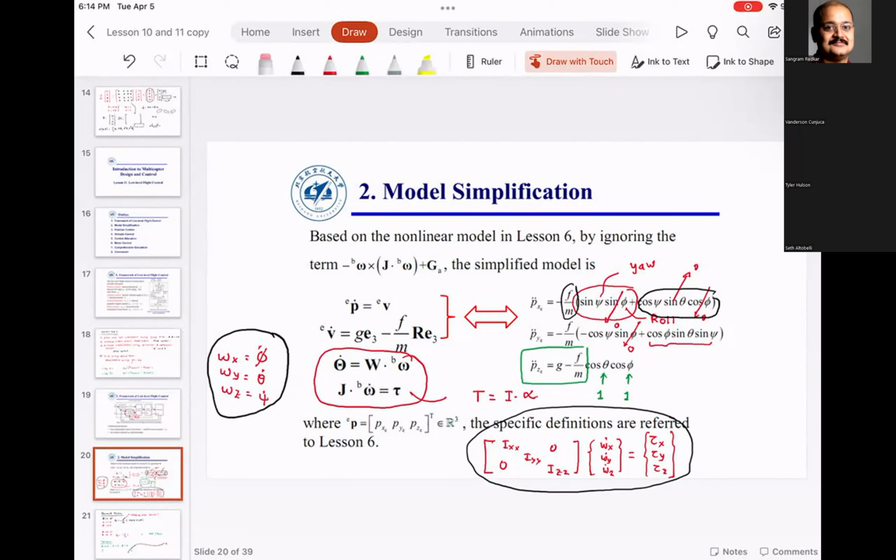If the Mambo is turning, and you make a non-zero pitch or non-zero roll, then you are going to have very complicated dynamics. So it will not be a pure translation in X or pure translation in Y. So somehow you need to maintain the value of heading, which is psi, to be 0, and then you have to either pitch it or roll it, and that would achieve the lateral motion.